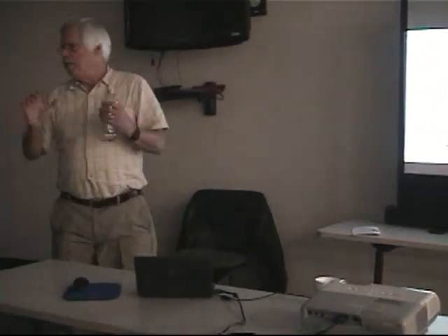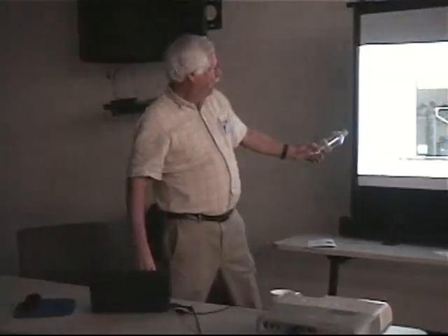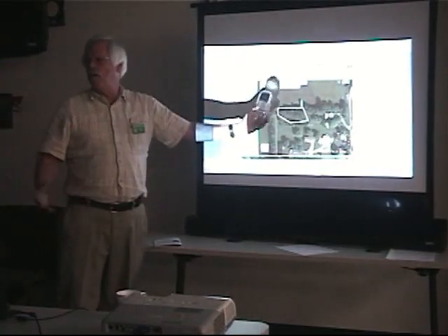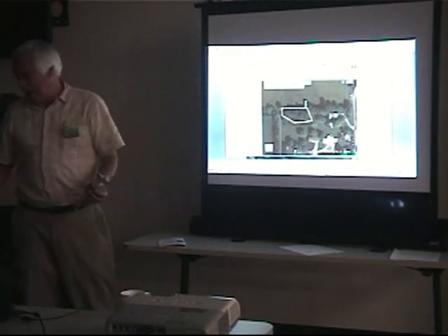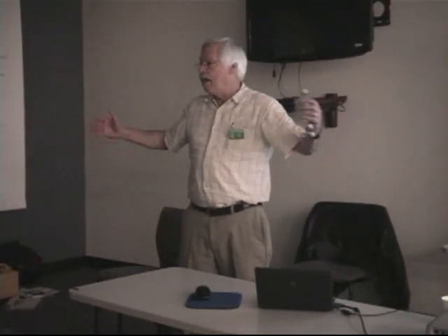I wanted to get on 80 meters with an omnidirectional antenna. So I marched out and started pacing off distances in this area where all the pine trees were. And when I did that, I realized that I could pretty easily get a loop that was about 500 feet long. I'd never been on 160 meters. I always wanted to be. 500 feet's about a wavelength.